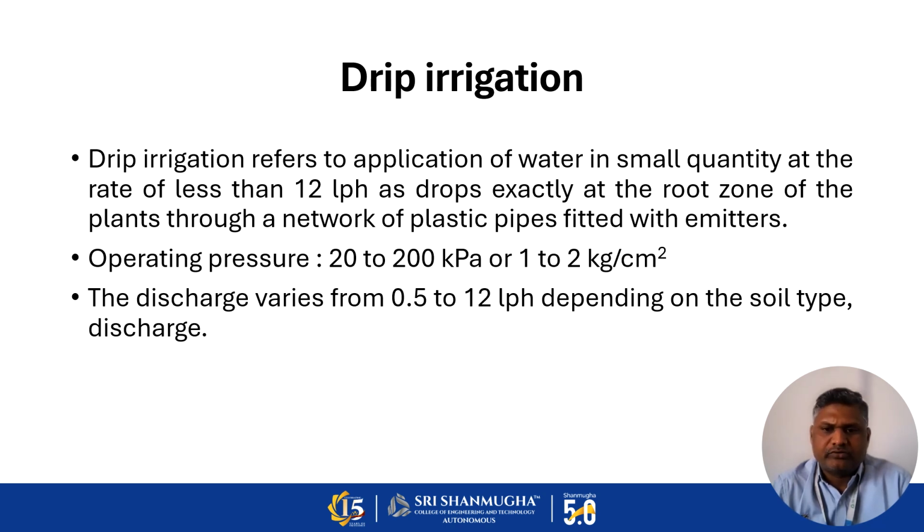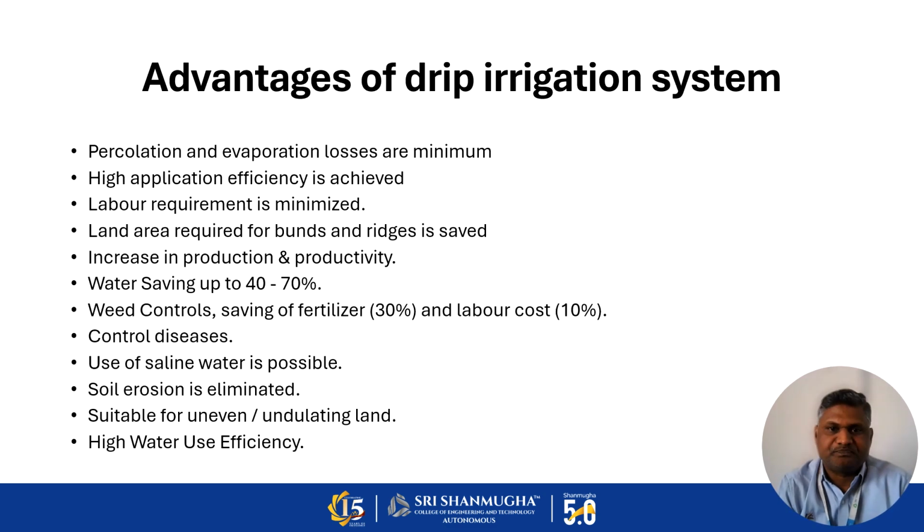But at the other end, soils like sandy soils are porous. Those soils have less lateral movement and greater vertical movement. So according to that we can choose the emitters for the drip irrigation system.